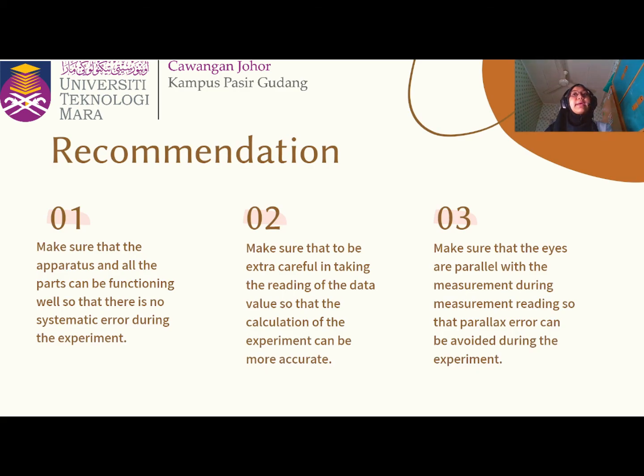Third, make sure that the eyes are parallel with the measurement during the measurement reading so that parallax error can be avoided during the experiment.